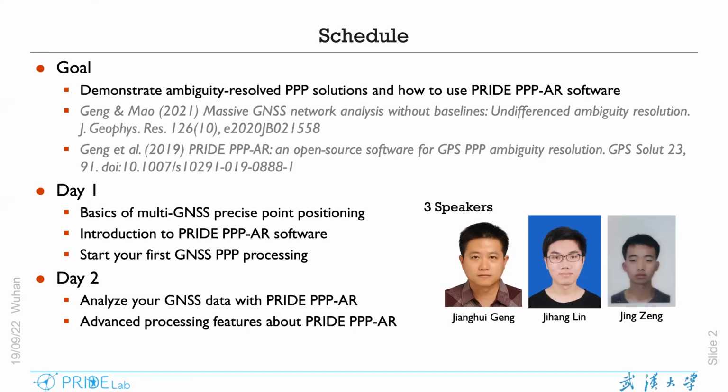We used to have network analysis using GPS. We have multiple stations, and we have to form baselines to achieve high-precision solutions. In this paper, we talk about why we had better use undifferenced solutions to obtain comparable position and precision to the traditional relative reference solutions.